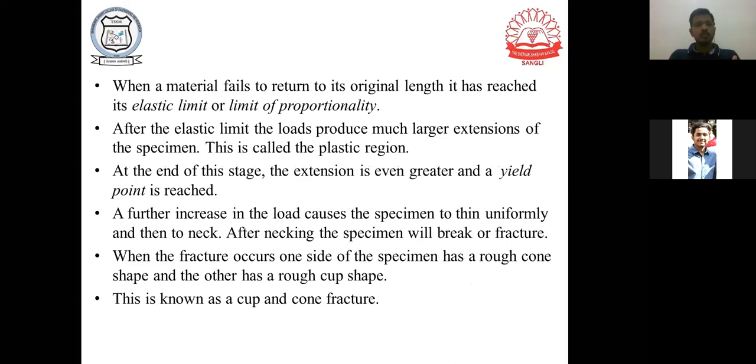So you go on increasing the load. Initially the material will be in the elastic limit. After a certain time, it will reach its yield point, and after the yield point, the material will leave its elastic limit and enter into the plastic deformation region.